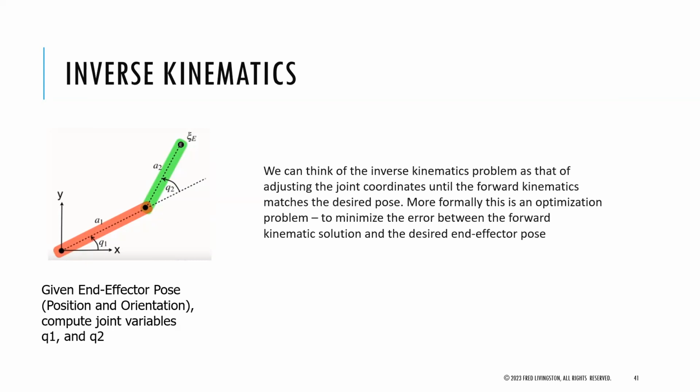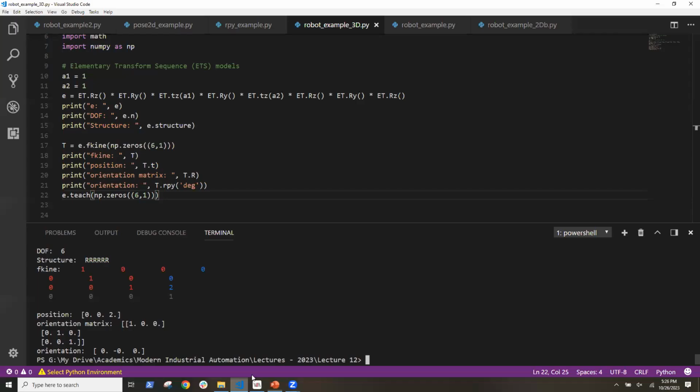that is your goal there. You can also, since it's a 4x4 matrix, just take the inverse of it, and you can also get a solution for certain degree of freedom robots there. It doesn't necessarily always work when you try to take an inverse of that matrix. So it may not be possible to get a solution, or we're going to have an approximate solution by doing this particular method here. And I want to show you what that looks like in Python.